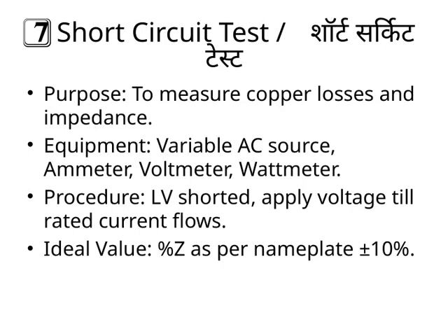Let's talk about the short circuit test, known in Hindi as short circuit test. The main purpose of this test is to measure the copper losses and the impedance of the transformer. It helps us understand how the transformer behaves under short-circuit conditions, which is crucial for assessing its efficiency and performance.